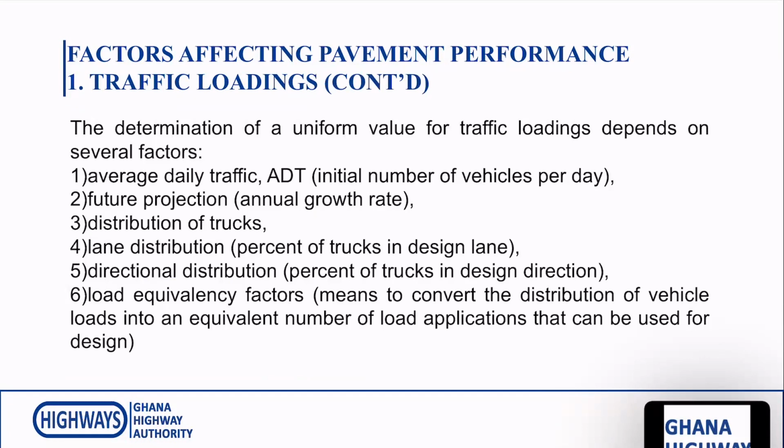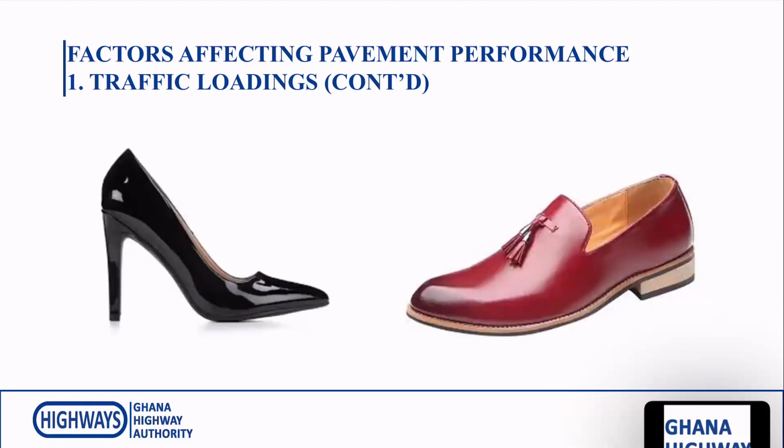You can talk of the volume when you are talking of the capacity, but for pavement design, it is the loading. And I would like to use this to show you what I mean by the loading. You see on the left, it's a lady's high heel shoe, and that is putting a lot of pressure on the ground. For that matter, if it steps on you, you will feel it. Whereas if my shoe on the right steps on your feet, you will not feel it much because the load is distributed better than the pointed load. This directly explains the effect of overloading at a point on the road.